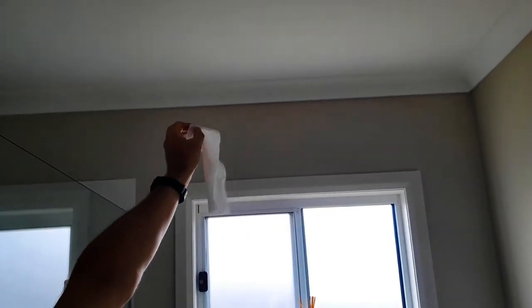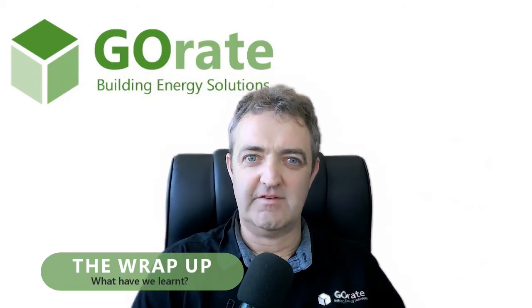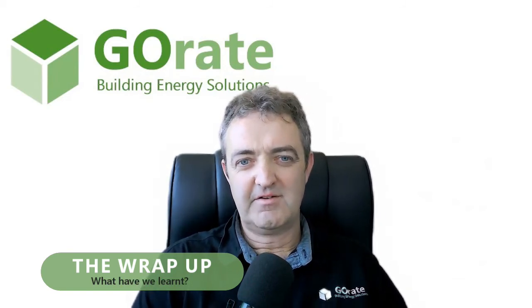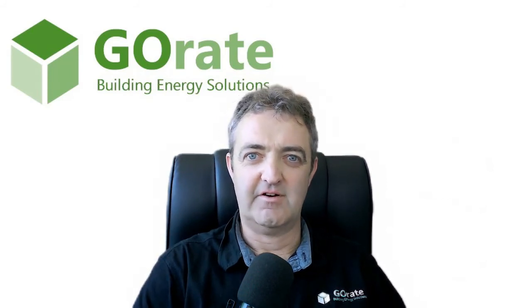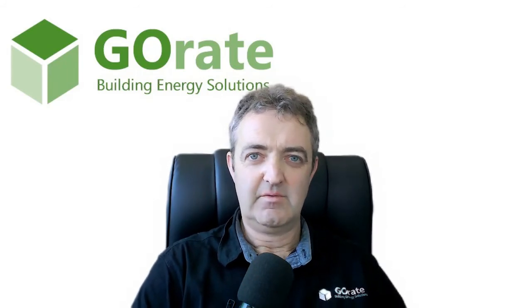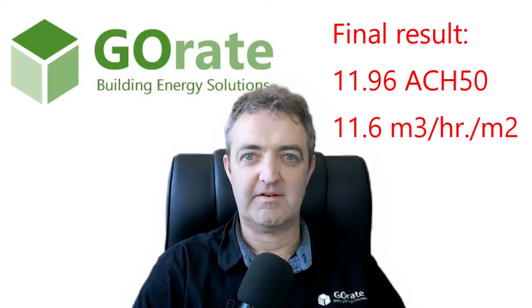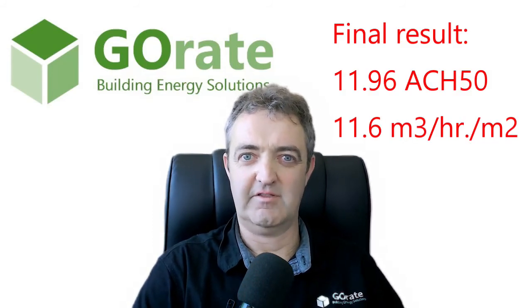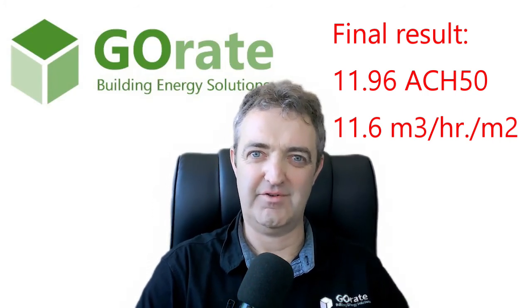That's pretty bad. So what have we learnt from doing the blower door test on this house? The purpose of testing this house was to see what our starting point was and to decide how to go forward building these identical houses again. We established that the house is pretty leaky, which is a problem. But on the upside, now we know where the leakage points are and we know what to do to make it better in the future.